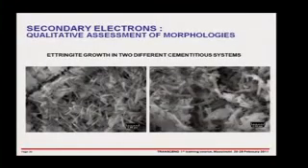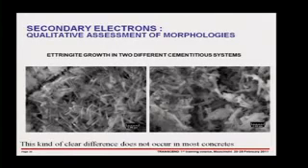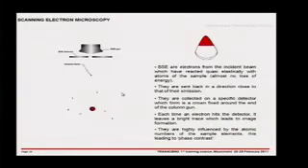There are certain exceptions. So, for example, this was a study we did where we had a very particular additive, and this particular additive made a dramatic change in terms of the way ettringite grew. So you can see here we've got very thick crystals of ettringite. Here we've got very thin ones. That was quite useful. But that's really the exception that proves the rule. Most of the time, I really say do not waste your time on secondary electron imaging. It's a waste of time.